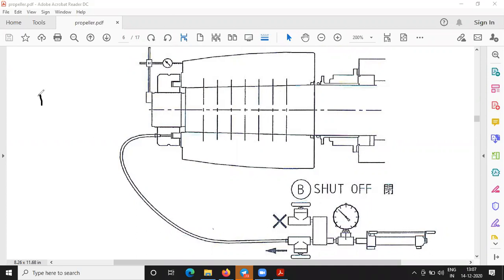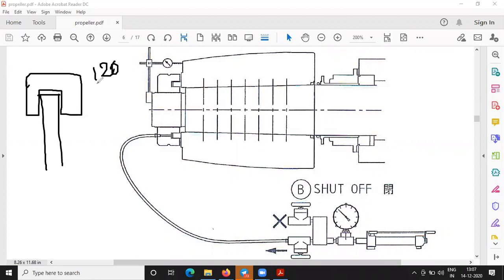Yes, sir. Continue, sir. In this stud method, we have the hydraulic jack. So it's not about the fact that we give 1200 bar. 1200 bar is not the limitation of the hydraulic jack. It is the limitation of the material of the stud. We can give 1500 also, but in that case the stud will get more elongated and it will go under plastic deformation.